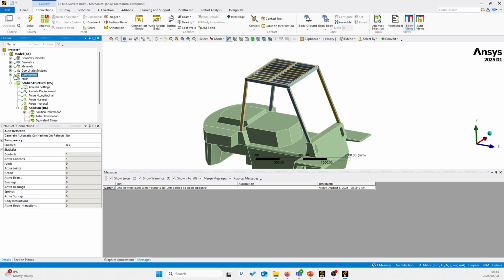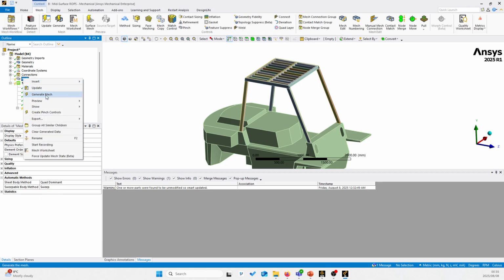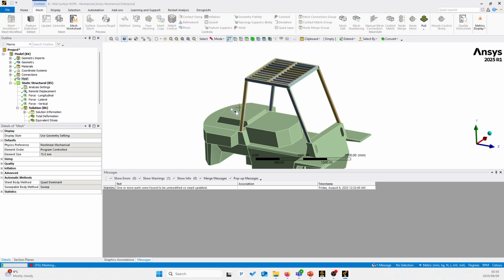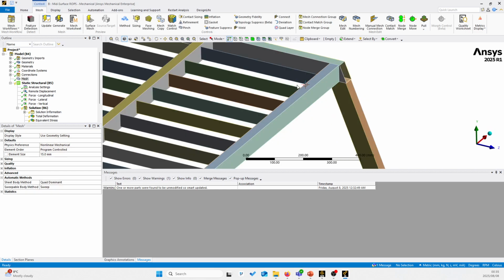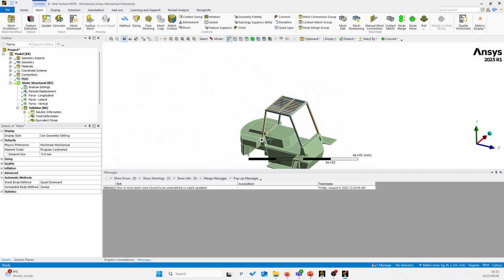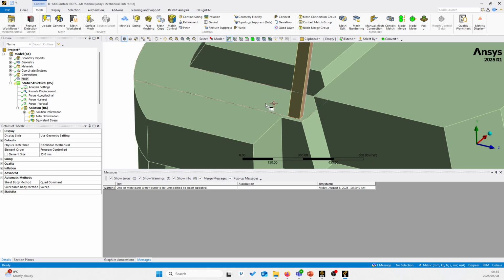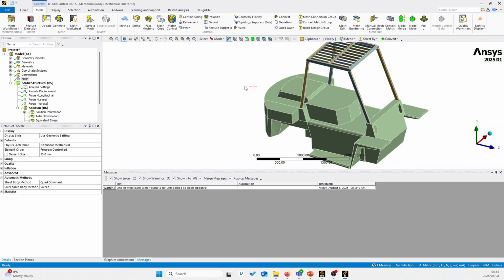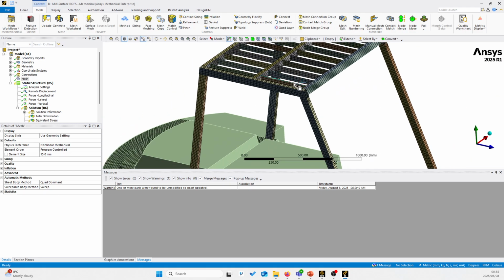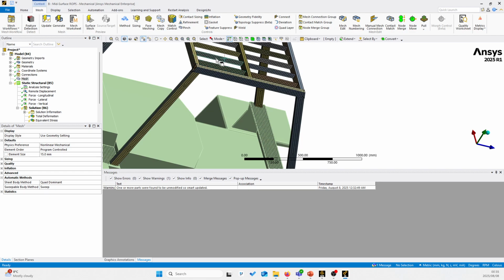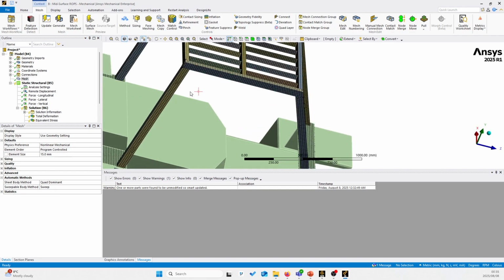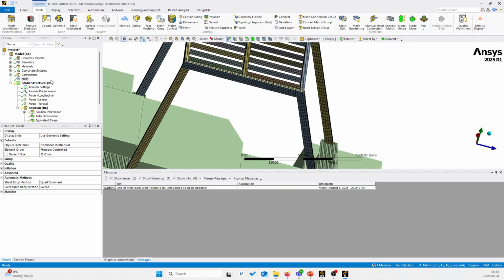And then afterwards, we can go into our meshing. We can quickly generate a mesh for this cabin. The mesh will be generated on these shell bodies, and also on the contact surfaces where we have our contacts between the cabin and the bottom part. We can go ahead and show that mesh here. You can see we have a very simple kind of mesh due to the modeling approach that we went for by using mid surfaces, and then we can refine this mesh later depending on the kind of results that we get back.